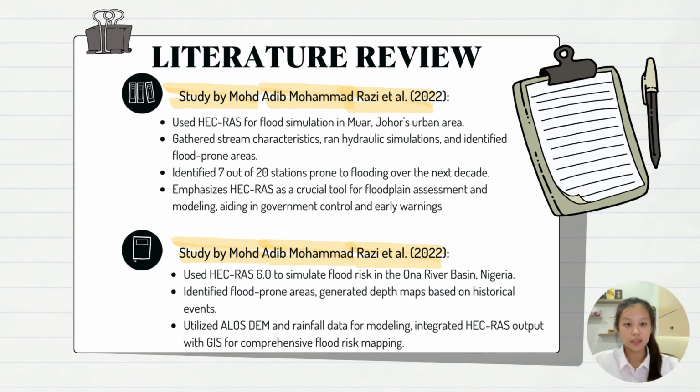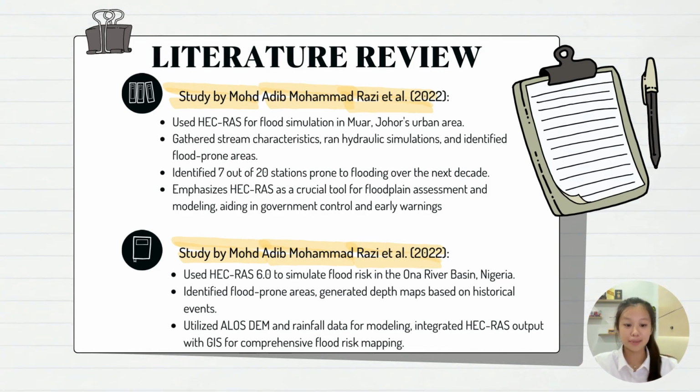However, we refer a lot to the study of Muhammad Adib because he used HEC-RAS for flood simulation in the urban area of Muar, Johor. He gathered stream characteristics, ran hydraulic simulations, and identified flood-prone areas. He identified 7 out of 20 stations prone to flooding over the next decade. He emphasized HEC-RAS as a crucial tool for floodplain assessment and modeling, aiding in government control and early warning.